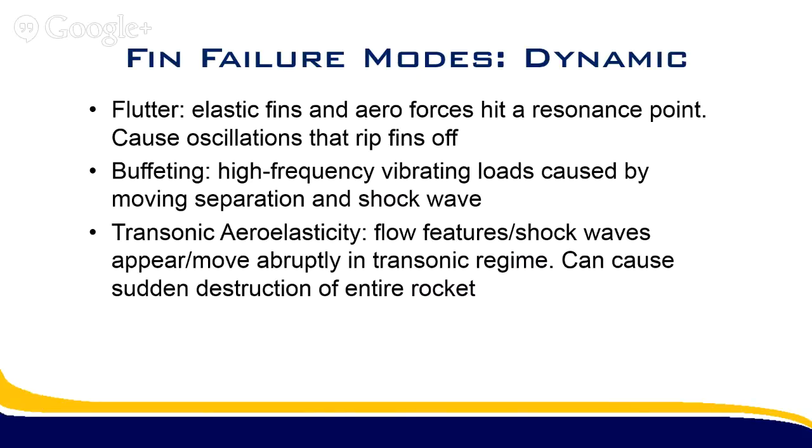Kind of hit a resonance point, so they start vibrating, and that vibration starts amplifying itself because it's at the correct frequency. That actually causes that resonant response, and eventually you start fluttering so much that it just rips the fins off or snaps them in half, which is of course a bad thing because you no longer have that fin surface to keep you stable. This has happened in many a rocket.